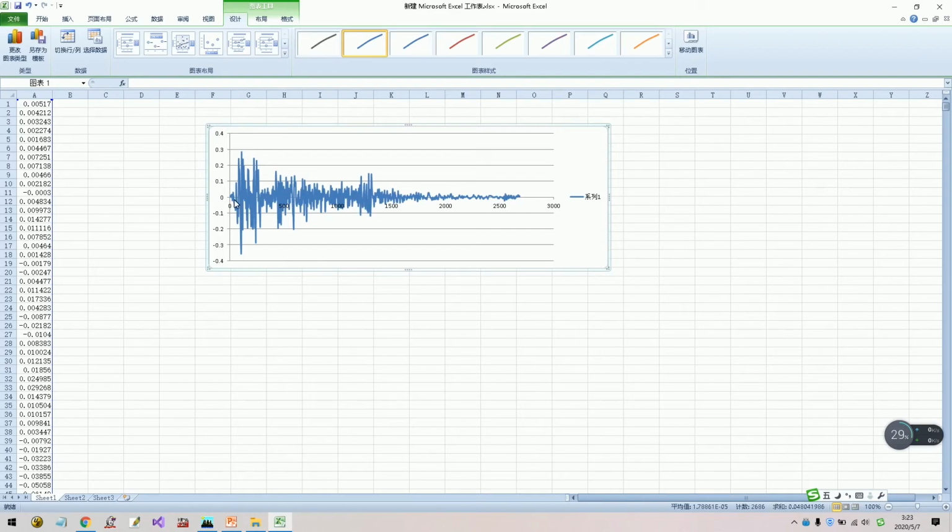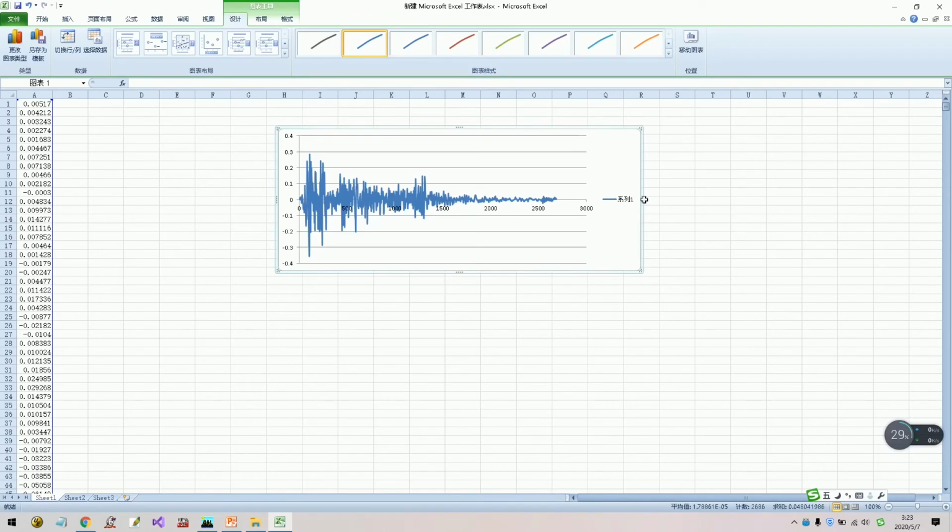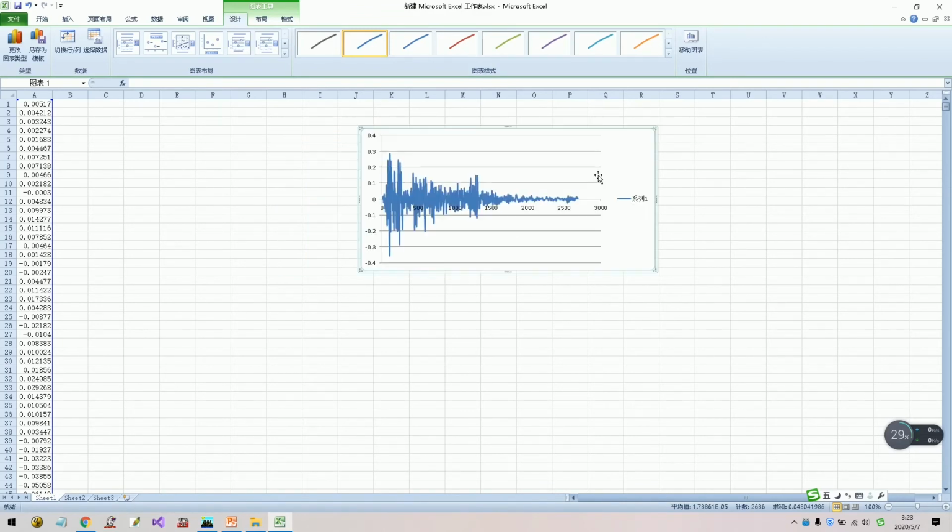For example, if the computer is quite slow, you need to get the maximum result. You can cut the duration. For example, we cut like this one is 25 or 28 seconds. We just cut here, cut 50 seconds. We cut the ground motion, but actually it's no meaning because we can set it in the time history analysis case.